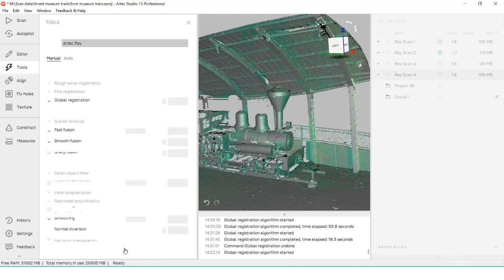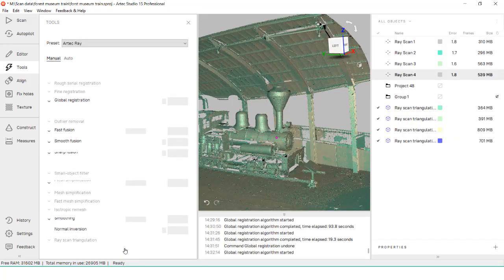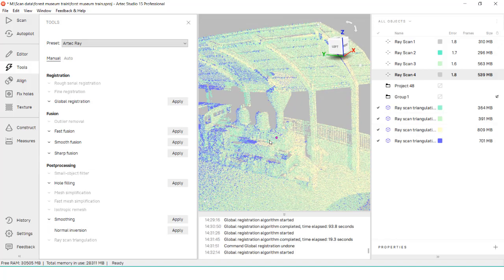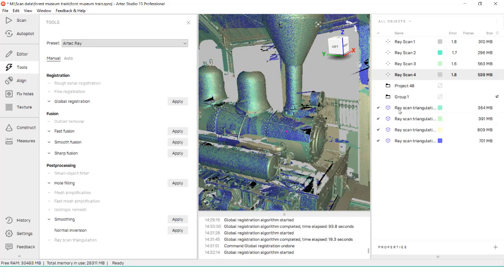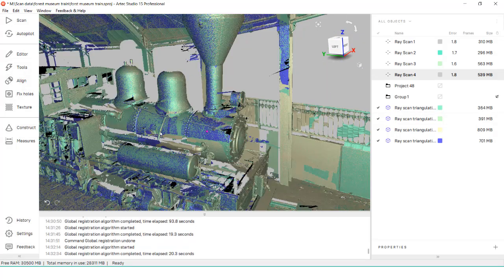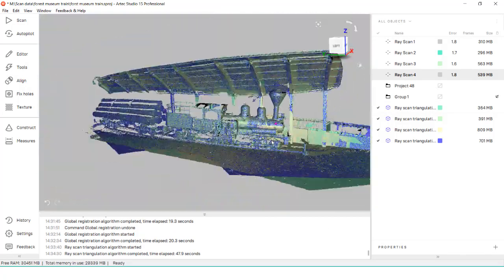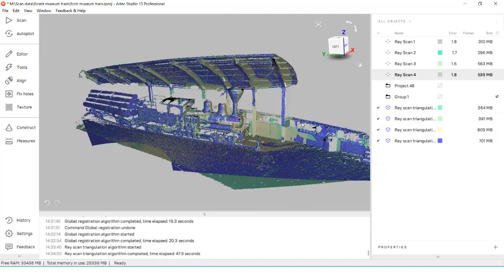The two modes in here, Simple and Adaptive, dictate the final size and quality of the polygons. Simple will create a mesh and run a decimation process automatically. The higher the level of decimation, the lower the quality of mesh will be. Adaptive creates a mesh based off of desired edge length, so the smaller this option is, the higher quality our mesh will be. The rest of the settings pertain to how much the mesh will filter out sharp angled triangles and noise, which I'll talk about in just a moment.